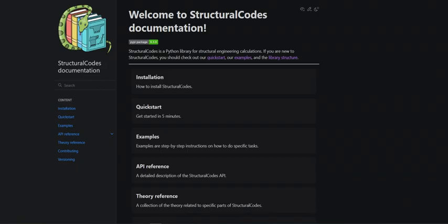When we switch to Visual Studio Code now, I will demonstrate what this does. So we've defined the perimeter of the cross section, which is a rectangular cross section. We've defined two points which represent our reinforcement, and then this final generic section function literally creates that 2D full section and combines everything together. So the geometry is already ready from this stage, but then we wrap it with some methods to work on it as well.